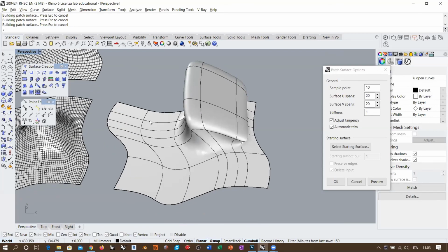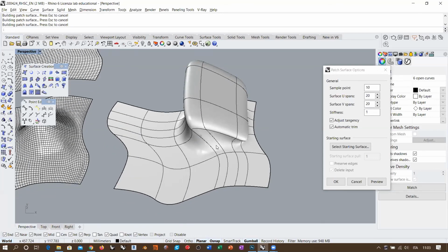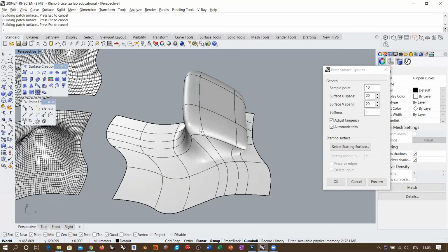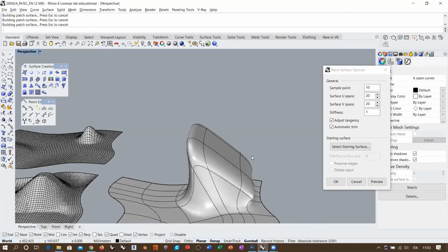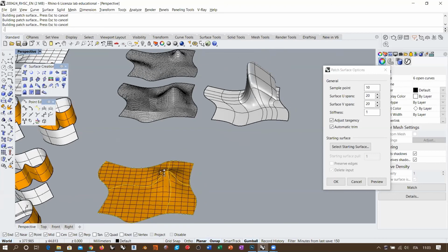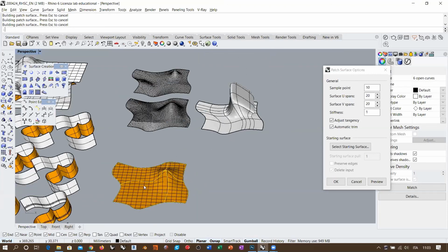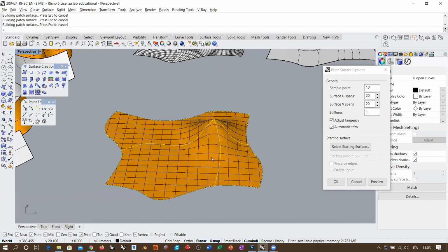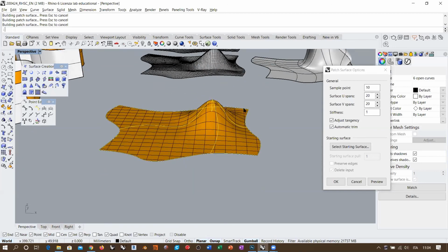We took a simple geometry with the right topology, and then created the topological variation by a denser representation of control points in order to create this deformation by pulling the control points. So the patch is similar to direct topological modeling, but it is not under control because the density of the control point network and the topology is determined automatically by this deformable rectangular surface, and the deformability is determined by the number of spans, and the actual deformation is determined by the patch automatically.